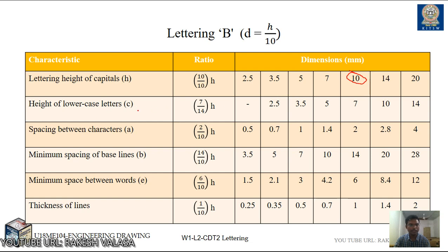Height of lowercase letters, h by 14 into h. Here, otherwise you can take 14 or 20. I am taking h by 14 into 10. That value is 7. Next, spacing between characters, 2 by 10 into h. H means 10. 10 get cancelled. The answer is 2.